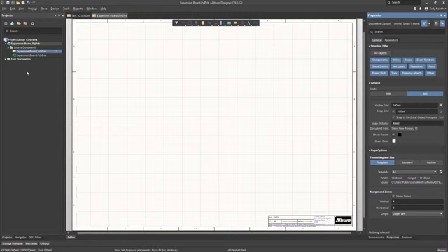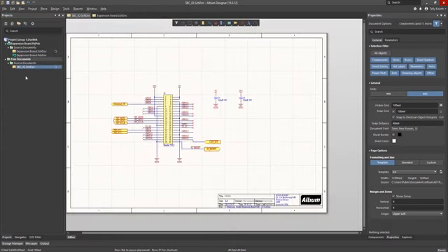In this instance, we will take advantage of adding an existing schematic to the project. If a schematic exists that has what you need, or close enough so that it requires little or no effort to be completed, this can save a lot of design time. To add an existing schematic to the project, we will need a local copy of the schematic in the same folder as the project. This was already done, and we have the schematic open under the Free Documents section.